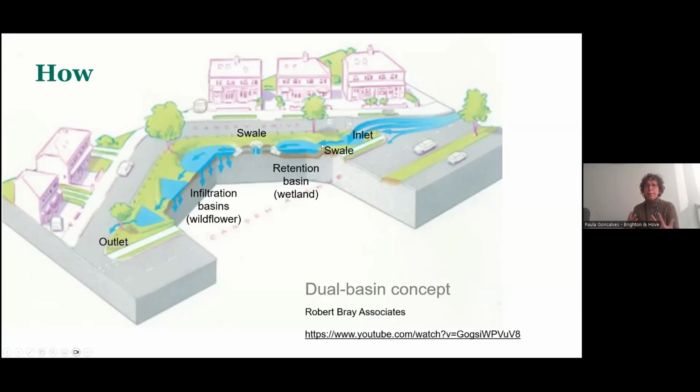This is a basin that's got a lining. In the first phase, we used plastic lining. In the second phase, because of the services, we had to do the traditional lining, which is compacted clay. Apparently any pond in the UK has this sort of lining, and it's more environmentally friendly.